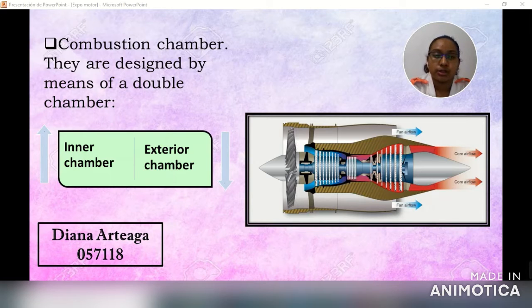In the subsequent step, a greater quantity of air is introduced to ensure complete combustion, and finally, before the gas exits to the expansion turbine, the rest of the compressed air is introduced to cool the exhaust gas and not damage the structure and downstream equipment.